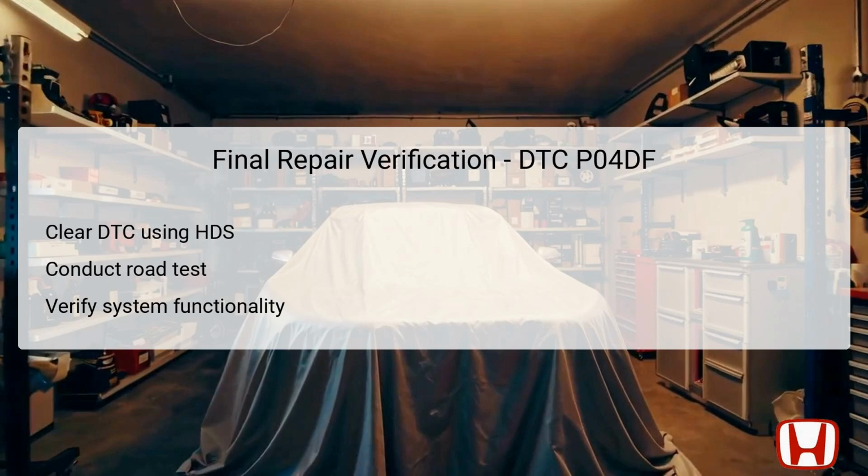Following the clearance, conduct a comprehensive road test to observe the vehicle's performance under various driving conditions. Pay attention to any related symptoms that may resurface, such as engine idling or fuel efficiency. Finally, recheck the functionality of the EVAP system using the HDS to ensure that it operates within the specified parameters. Successful clearance of the DTC and normal operation post-repair confirm that the issues have been resolved effectively.